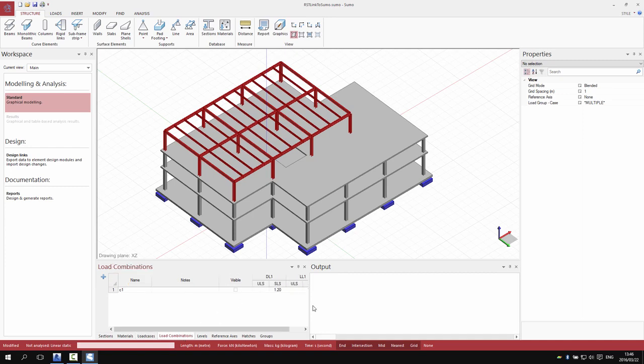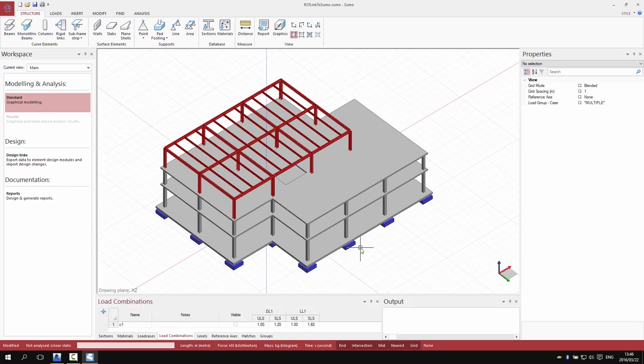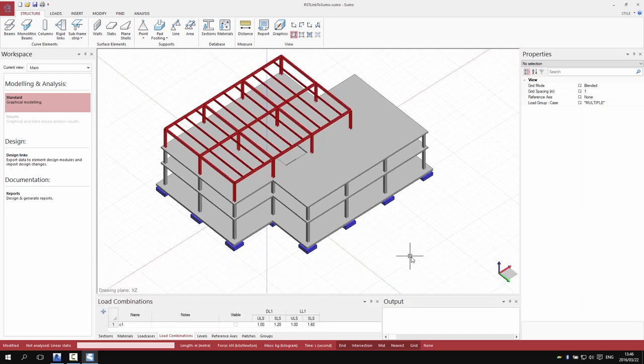In terms of load combinations, we can also set up load combinations. For instance, in this one, I've created a load combination 1 between my dead load and my live load. I can also go and add my safety factors, which will then automatically calculate those for me. Once I'm ready, I can then start placing my loads on my structure.